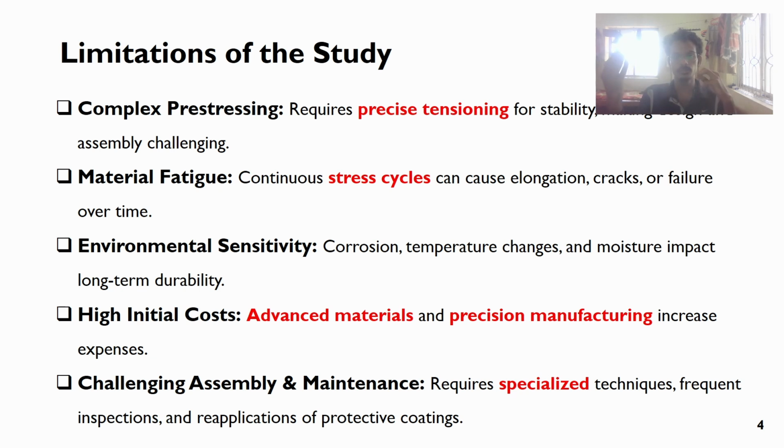Due to corrosion and temperature changes, there may be a slight problem with the durability of the material. Advanced materials are also required in some sense, because we can use a hot roll section at the bottom, and above we'll use cable members to take the sheet load. Normally, in the conventional approach, we use hot roll sections throughout. Here we are going to reduce this cost.